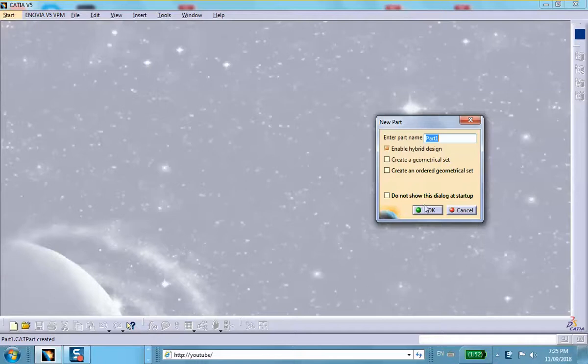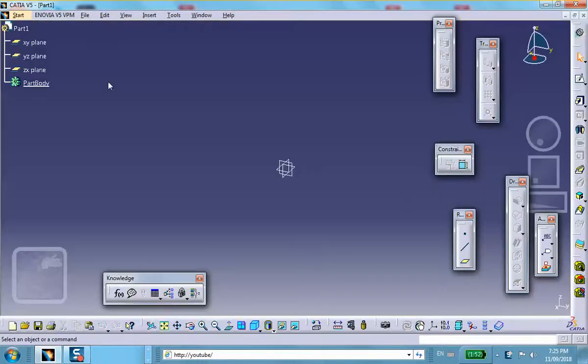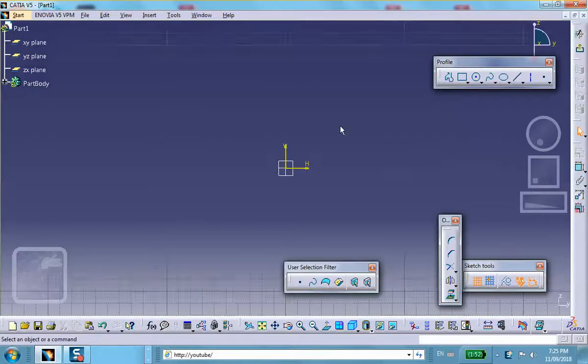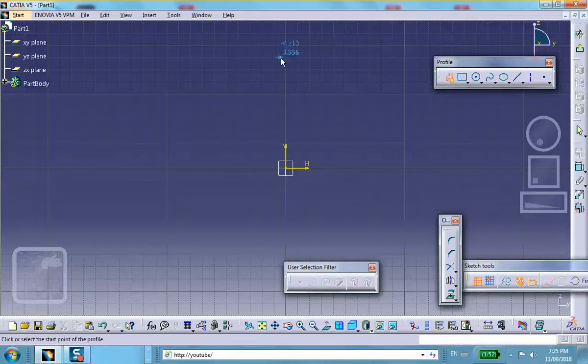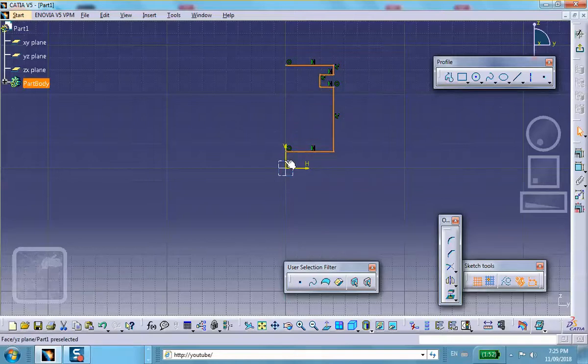Alright. On a convenient plane, say on this vertical plane, I will sketch. Well, I can sketch the profile like this, and let me quickly do that and then show you that we can do it a different way. So something like that. This is going to be the section of the piston before I revolve it, and then revolve that around this axis. But at the same time, I want to show you a different trick.